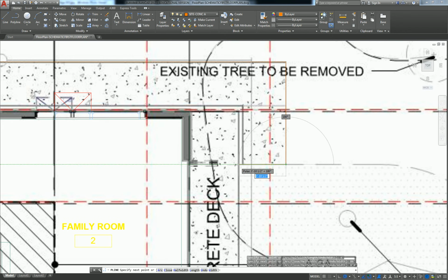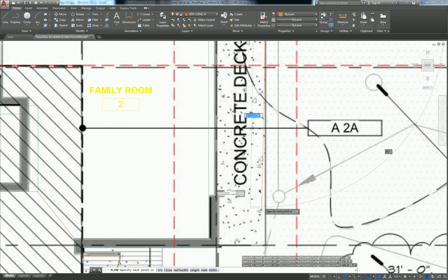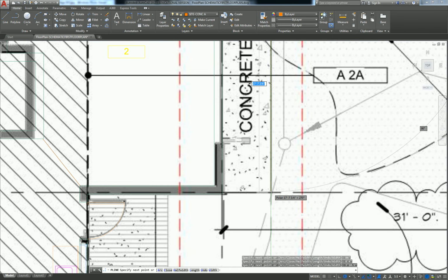Looks like there's a mow strip in there. So this one's probably, I'm okay with 1/2 inches. When it comes to site plan stuff, I'm not super okay with 1/4 inch values, but I would be okay with 1/2 inches. So this is going to be 3 feet 10.5. And then down here, 17 feet 8 inches.